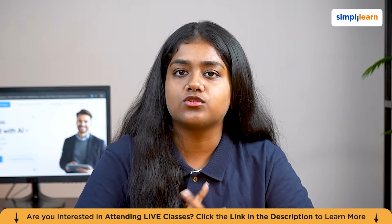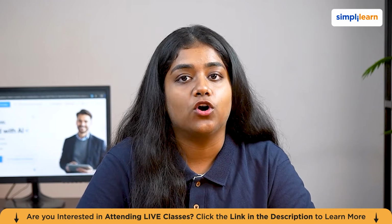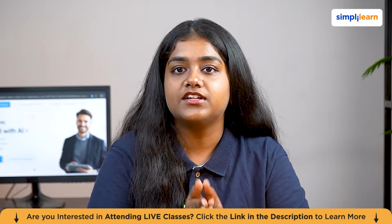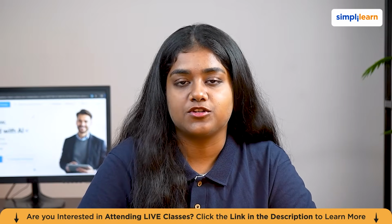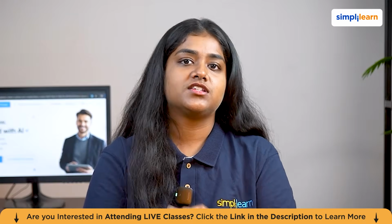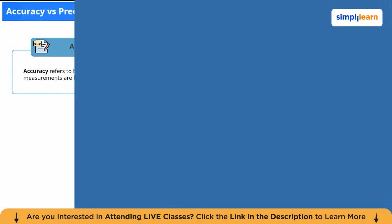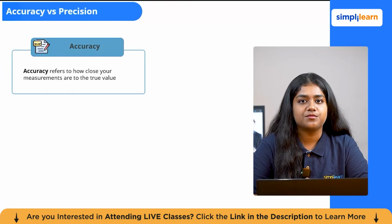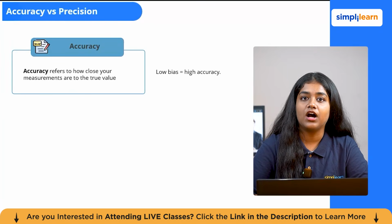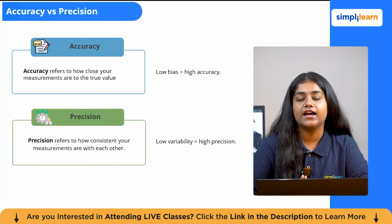So let me tell you the sources of variability. It can come from the instrument's precision, differences between operators, changes in temperature or humidity, part positioning, fixture setup, or unclear measurement procedures. Standardizing the method helps reduce this variation. Now let's talk about accuracy versus precision, because the distinction is crucial and it's often confused. So accuracy refers to how close your measurements are to the true value. Low bias means high accuracy. And precision refers to how consistent your measurements are with each other. Low variability means high precision.